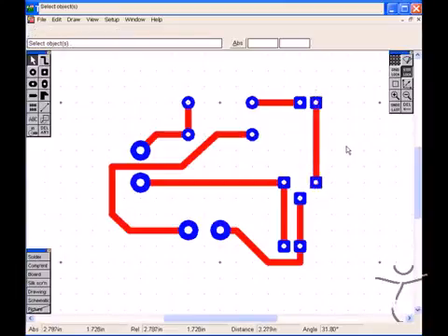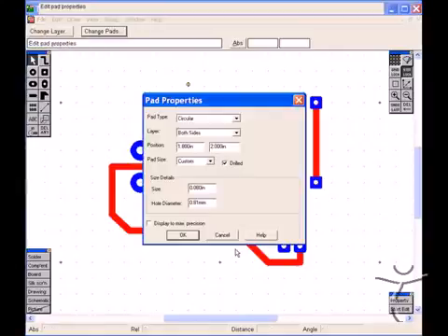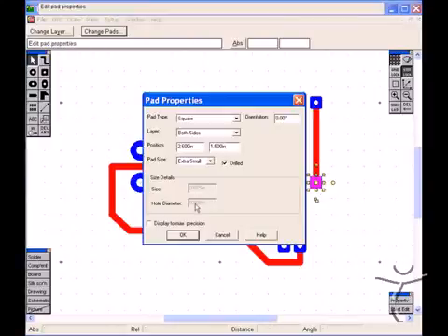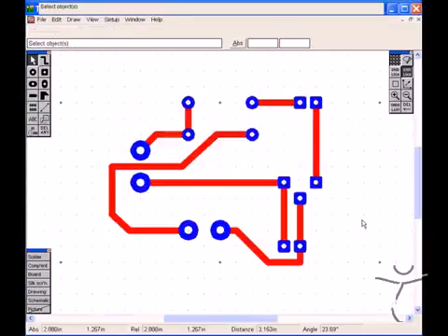So now it's a matter of going and doing the engraving, but it's also worthwhile checking the size of the holes. So if we go here and check the property, it's 0.81 millimeters. This hole here is 0.8. So if we're not careful, we'll do our selection of our drills, we'll get the 0.81, but we won't get the 0.8.